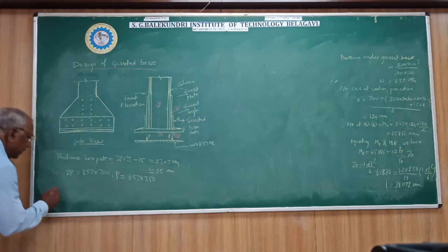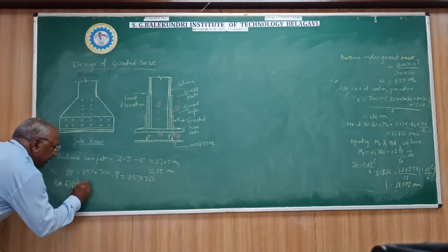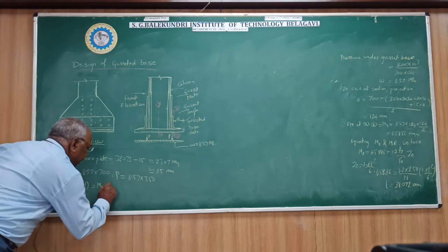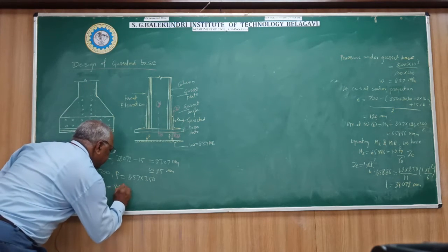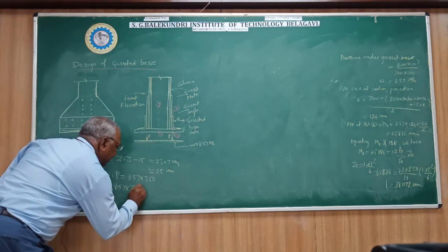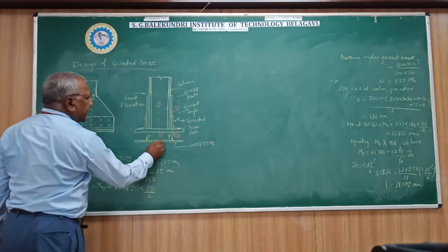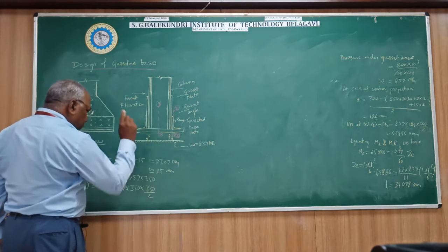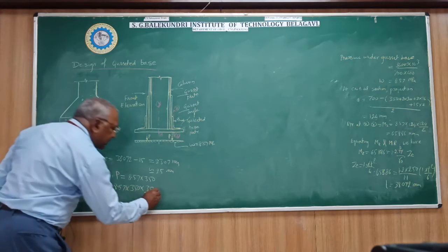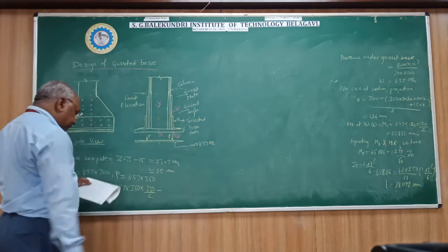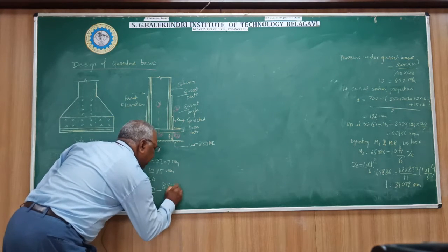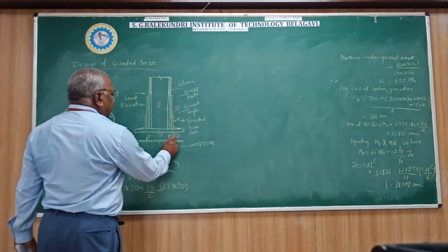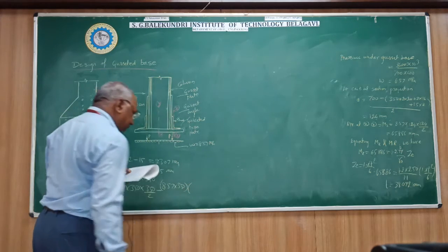The bending moment at the YY section is MYY equal to 8.57 into 350 into 350 by 2, the point of CG being at half of 350, minus the moment produced by the point load P. This is 8.57 into 350, the value of P, into the lever arm for P from the point of the load to the center of the plate, that is 350 by 2.